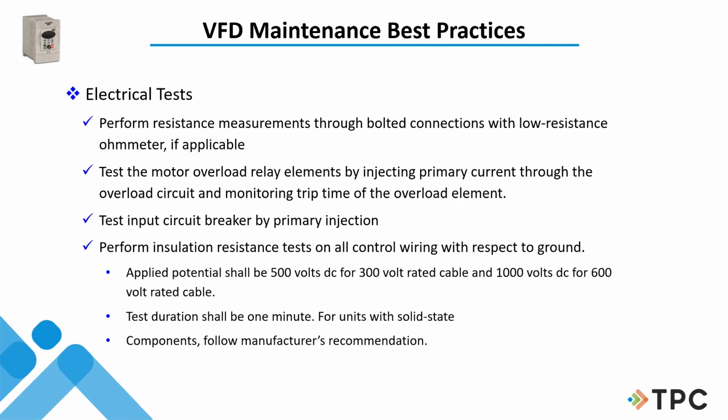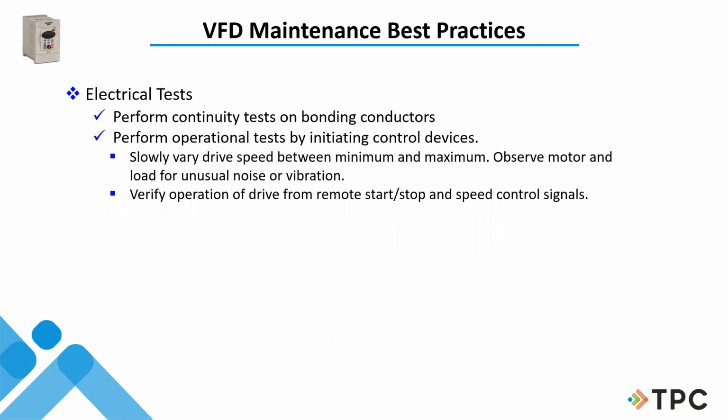Electrical tests, very important on the motor, on the drive. When you started it up, what was the voltage coming in? What was the voltage going out? If you have that information, it's very important to get it down in a technical book someplace. Maybe you got an engineering book or something that you can put this information in, because when things go bad or we start tripping out, well, let's see, do we have the voltage we had when we started? You know, what's the temperature? All those things are important to get through.